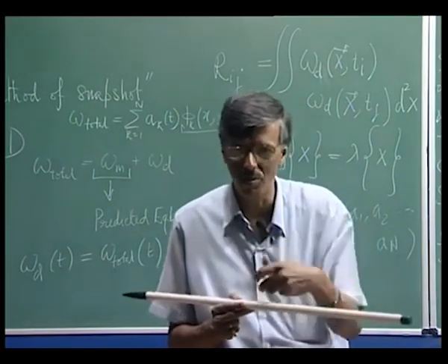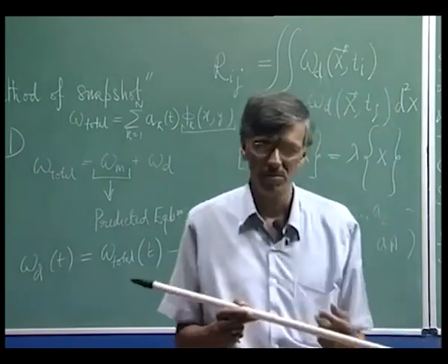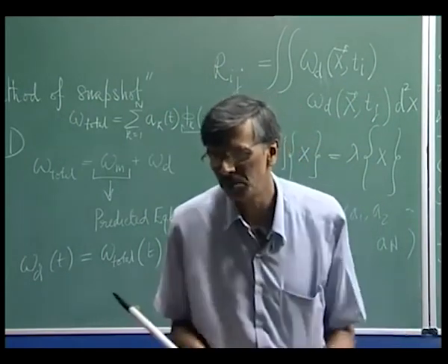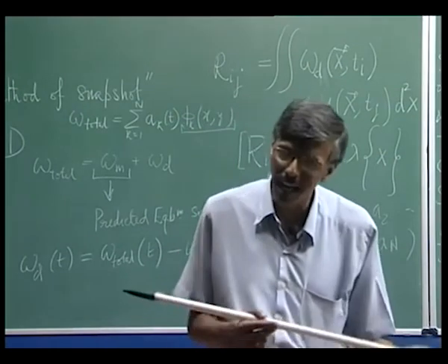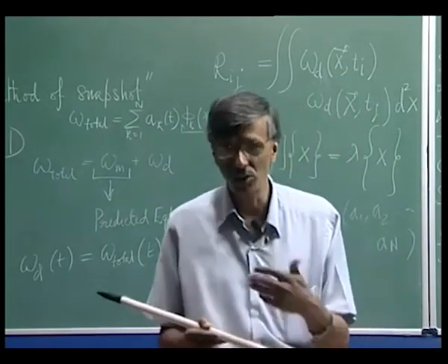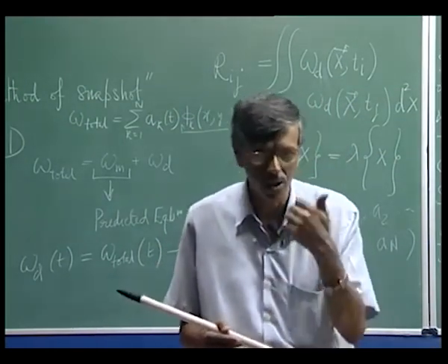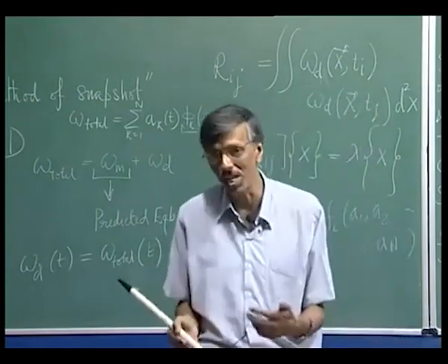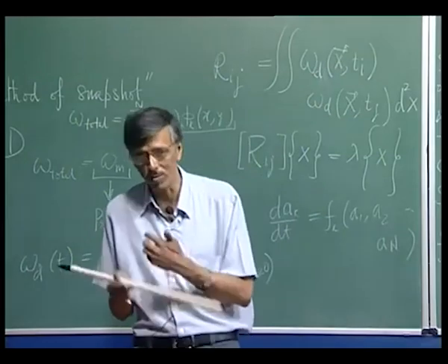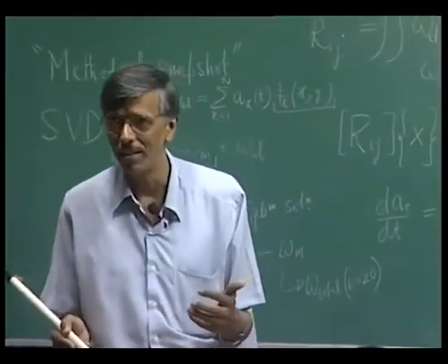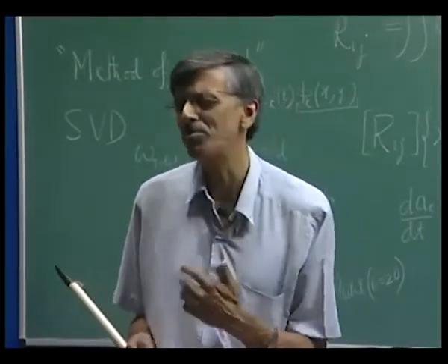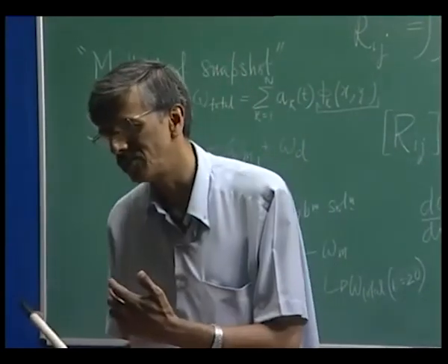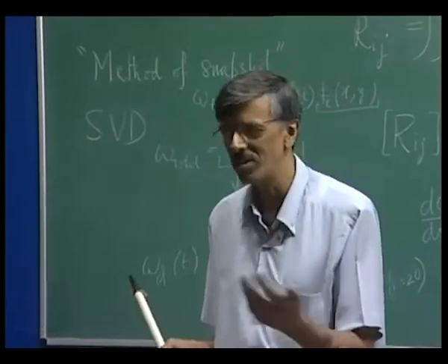Although my oncoming flow Mach number could be say 0.7, 0.8, the component normal to the leading edge can be kept say less than 0.4, and then the resultant shocks will not be normal shocks, they would be oblique shocks and weaker. There is also a possibility which came about much later, that you make the shock absolutely weak, and those are called supercritical wings. They came about in the 60s and 70s.